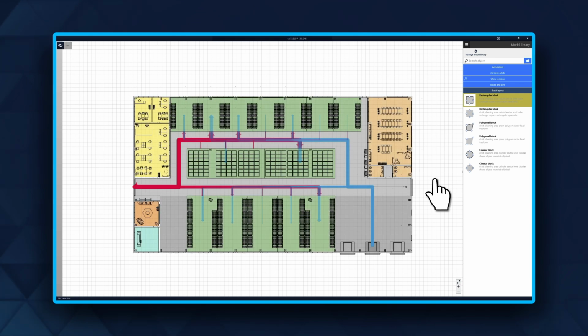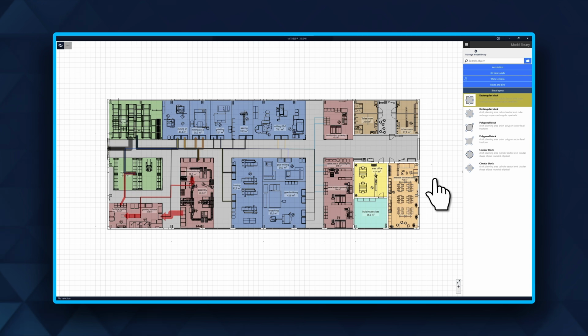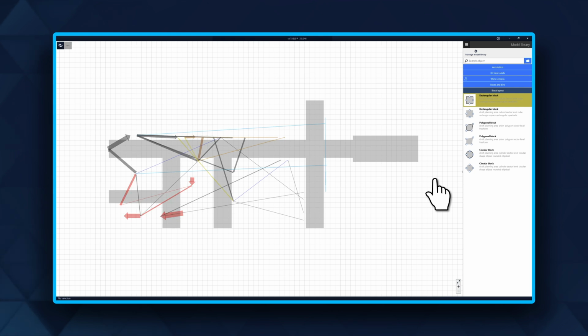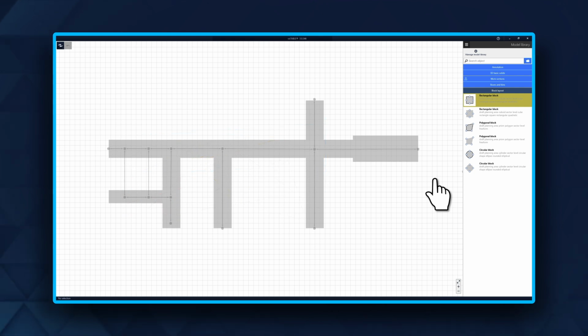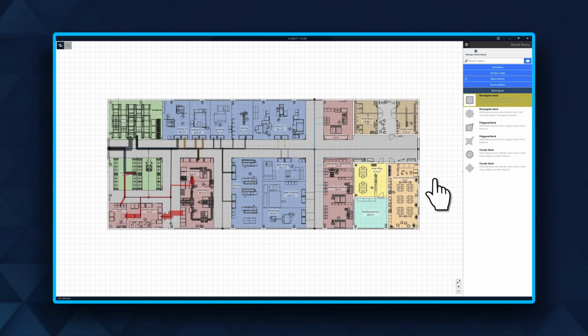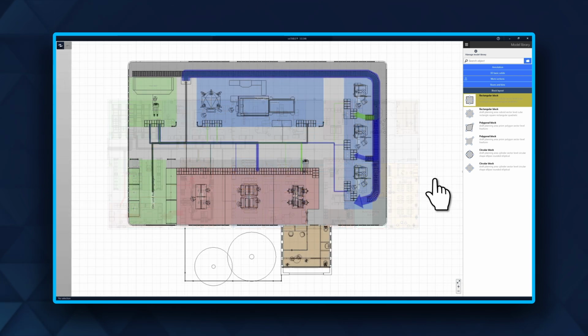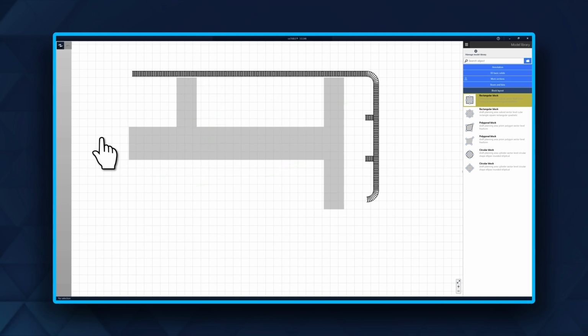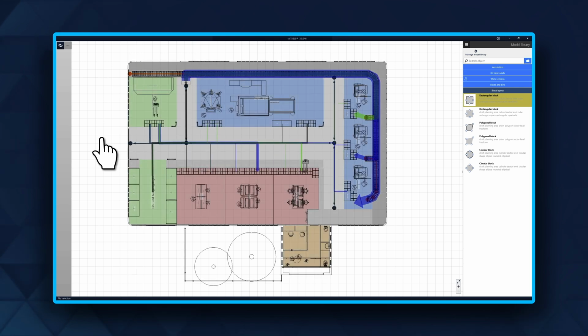the material flow. So the procedure to create material flow visualization is always: create material flows as direct connections, define transport areas, create transport networks within the defined transport areas. Switch on material flows bound to the path options of the transport network. This principle holds true even for specialized transport areas such as conveyor systems. When you properly define the transport networks, the material flows will make the best use of it.